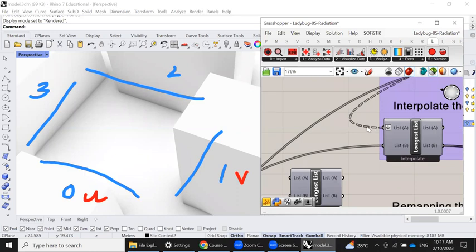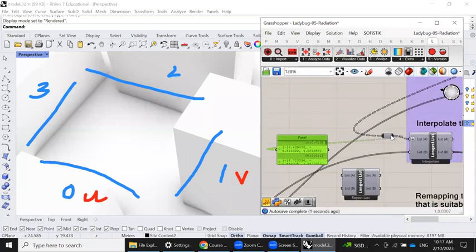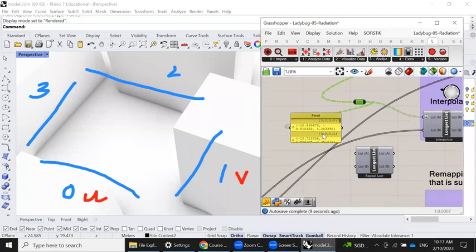This information is coming from far, far away, correct? Sometimes when you open your friend's file or your colleague's file, it's very annoying to go and find it. So the trick is to just double click on this connection, this curve, this squiggly thing, and it will create a relay. From there, you can transfer it to what you want to do next. You don't have to go and find the original connection. So this is the smart way of doing these things.